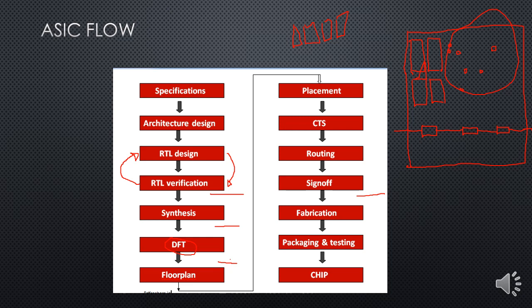We need this because we need to store the data present here. Once someone provides the input, we store it in the first memory element and start processing it. Then it goes to the next state, the second flip-flop, and based upon some processing it goes to the third state, and from this third state to the output. So now we have 3 stages and three memory elements here.